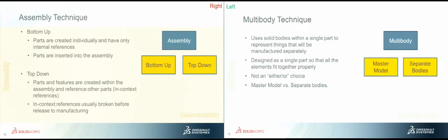But there's a couple of different techniques you can use within that context. The two main ones: there's weldments, where everything fits together in one part, and they all have separate bodies, but there's not really any flow between the two parts. In other words, you don't need to put them both together in the same part file to get a smooth shape between your parts.